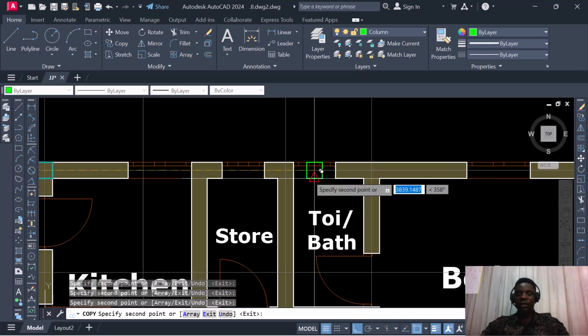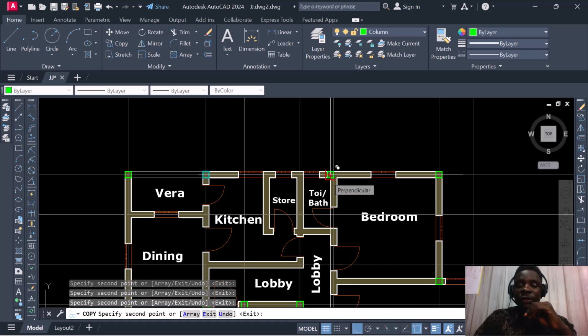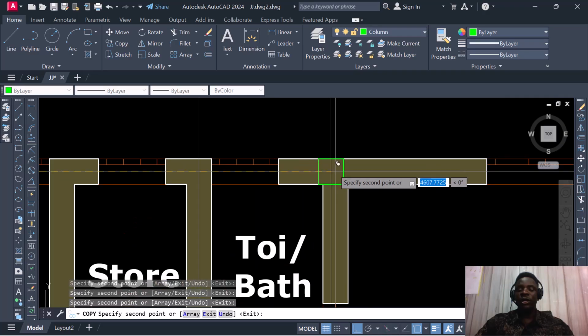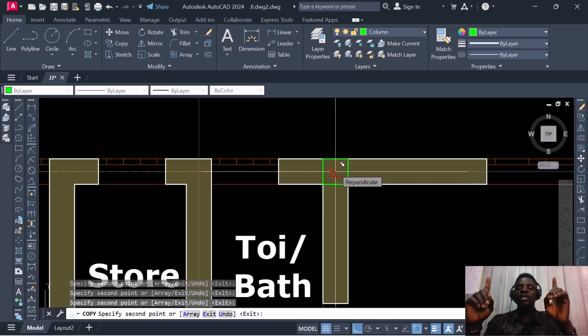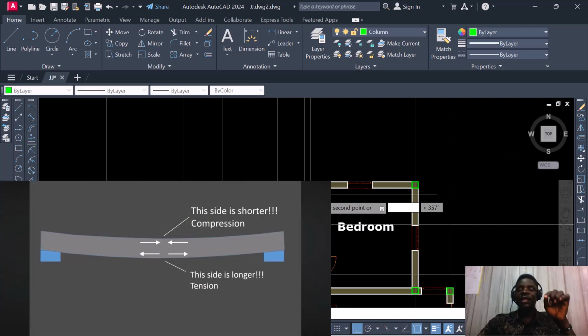So looking at this span, and mind you, when we are creating our support, we are looking at how we can arrange a cantilever, we can arrange a support setting of 5 meter. We don't want to exceed 5 meter. We just want to keep it simple, because the wider your support, the higher the number of reinforcement. All right, the higher the deflection, because when you have a continuous span, or the span of your structure spaced apart, then you're going to have a high tendency of having a lot of compression at the bottom area.